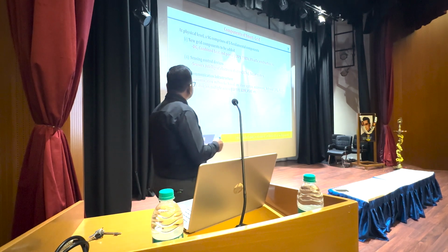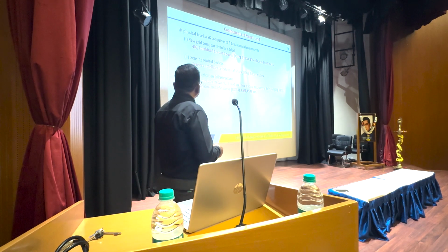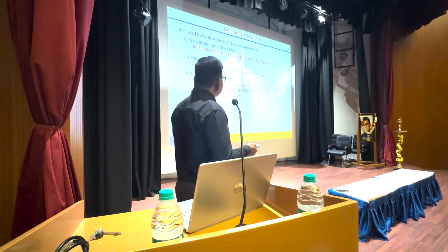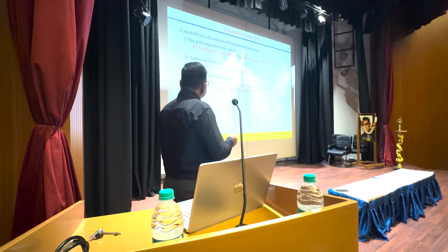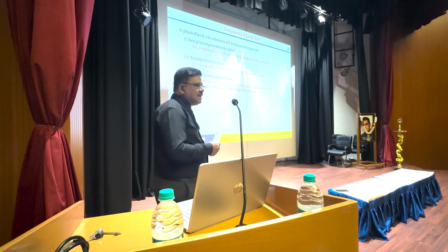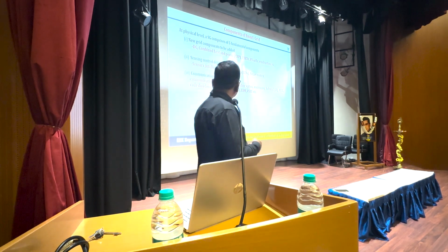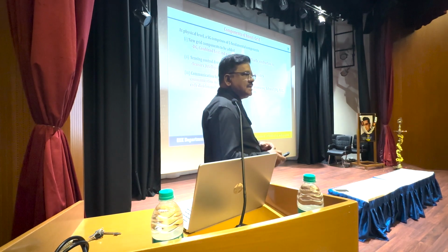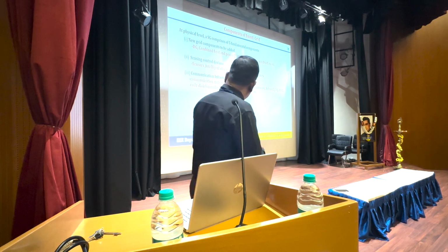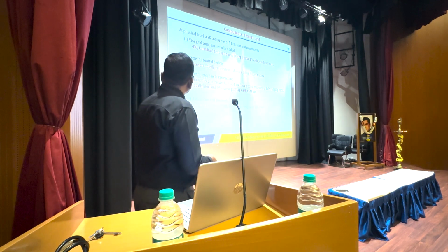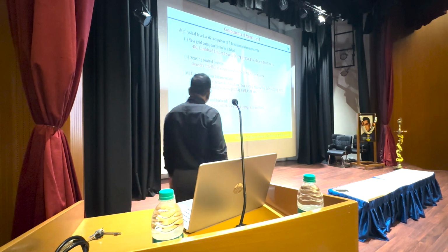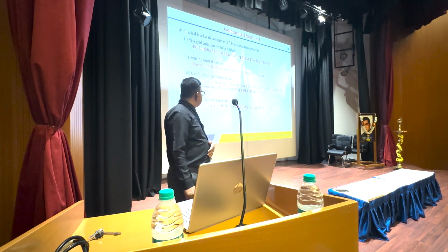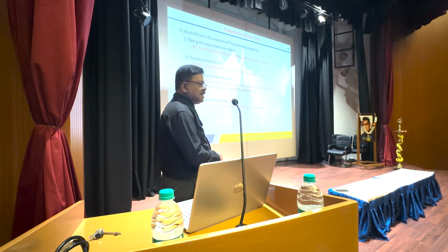Then the third one is communication infrastructure. The communication network may be based on fiber optics, microwave, infrared, PLCC, etc. VSAT is also included, which has been implemented in Karnataka. Now new communication technologies, cellular technologies, are also being implemented in the smart grid. Then automation and backend. At this level, we will have high-end servers, middleware, data storage units, DMS.